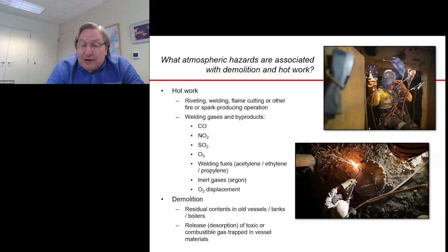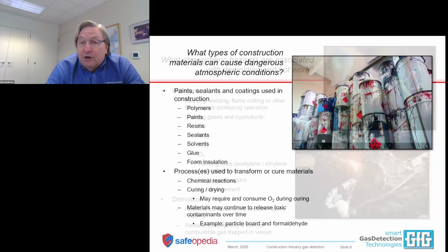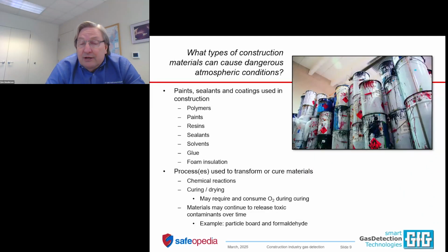Demolition. Here, we're also interested in, or need to be mindful of, residual contents in old vessels, tanks, and boilers that can actually impregnate the ground. It can impregnate the wall of the tank itself. It's trapped in there, just waiting for you to heat it up with a cutting torch to get back into the air where it can cause harm.